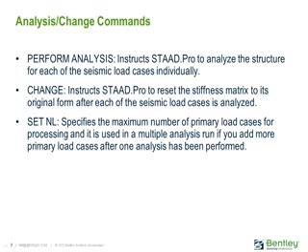Finally, we will also specify the set NL command, and this will be required in our model. This specifies the maximum number of primary load cases for processing, and it is used in a multiple analysis run if you add more primary load cases after one analysis has been performed. Of course, we'll be adding several perform analysis commands, and we do have load cases after them, and that's why we'll be required to have the set NL command.